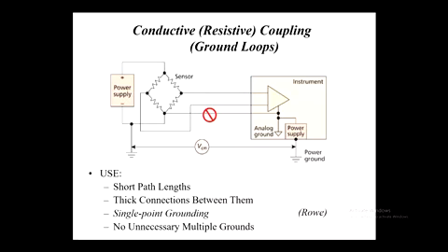a resistive coupling through a ground loop, and that is to say, when there are two earths, and it might have been better if I'd used a different symbol for a ground for one of these to show that it's not exactly the same ground. And the idea is that, supposing in this room we've got two power points, mains points right on opposite sides. Ostensibly the grounds of those two, the green wire or the green-yellow wire, are connected together, but in so doing there is some distance between the two, so there will be some finite, albeit very small, resistance between those two grounds.